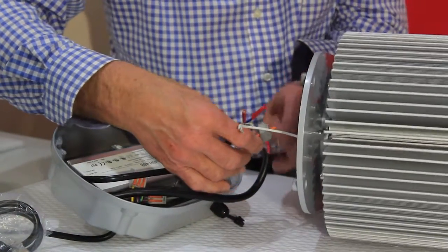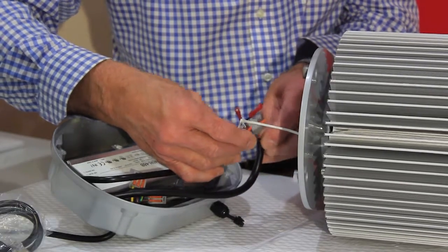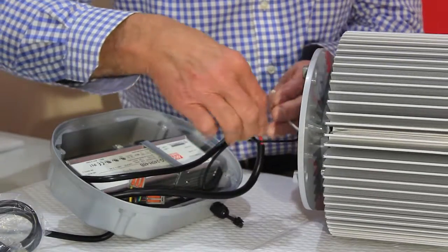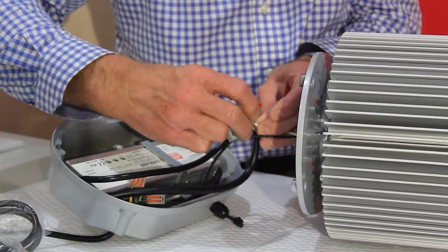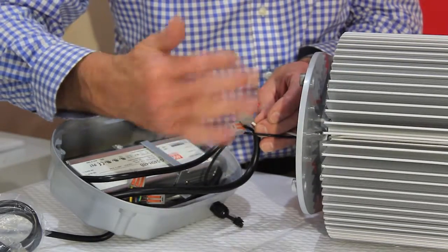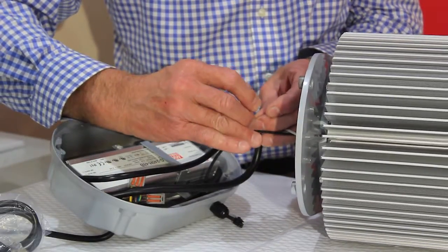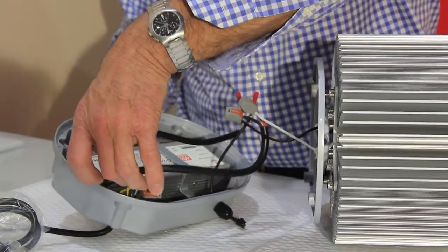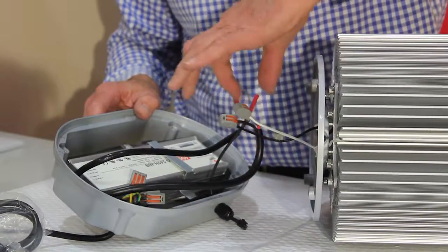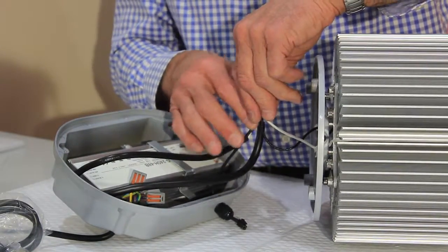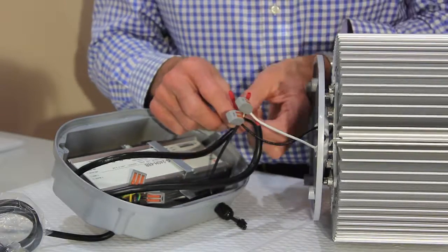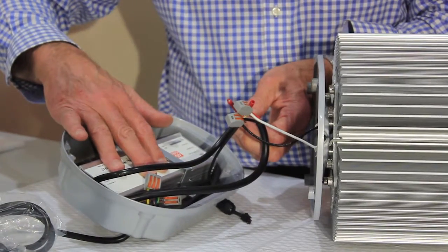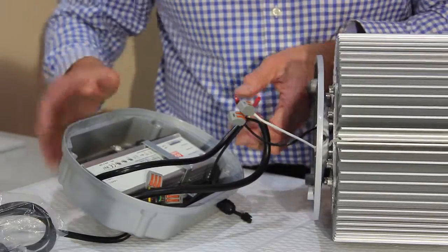Now we pop the black in here into the quick connector, lock that down. The white's the same. LED won't go if you get the polarity mixed up. And there we have that one locked down. So what we've got now is the power out of here, power into the letter A, and we've taken a supply off for our control, and the control wires have picked up the control for the 0 to 10 volt dimmable driver. So there we are.